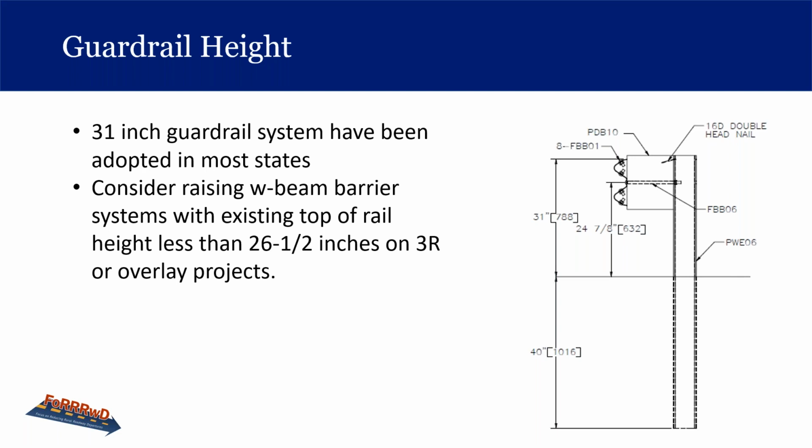The MGS represents the combination of these factors. The MGS has also been crash tested with 8-inch blockouts, and the Texas DOT is currently preparing to submit a request for eligibility. Other systems were subsequently developed that also have a 31-inch mounting height.